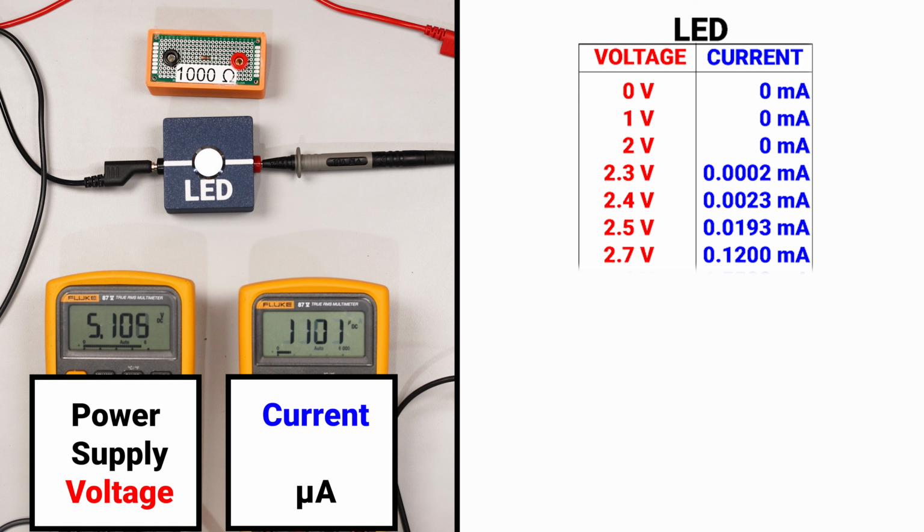1,000-ish microamps on the right meter. So I'm going to switch back to milliamps, and we can see that kind of relationship that's occurring. So at 6 volts, we're about 2 milliamps, and we'll continue to move forward.